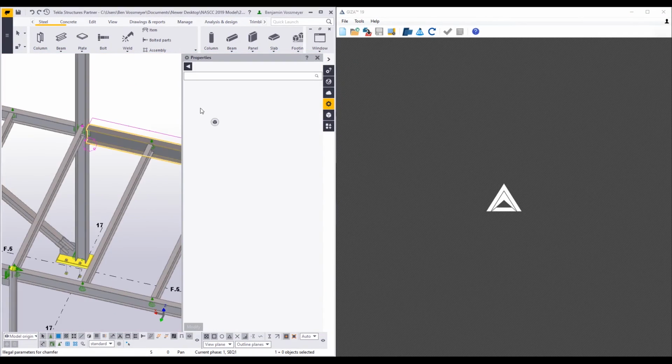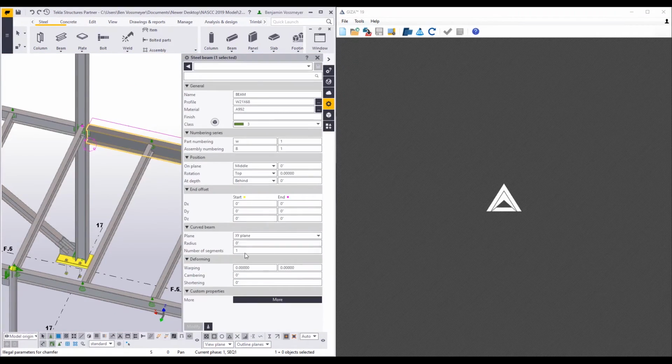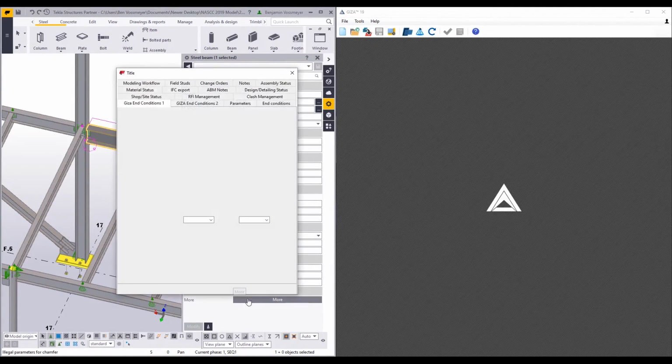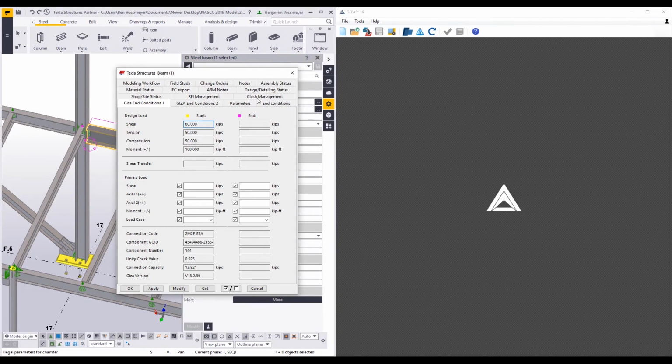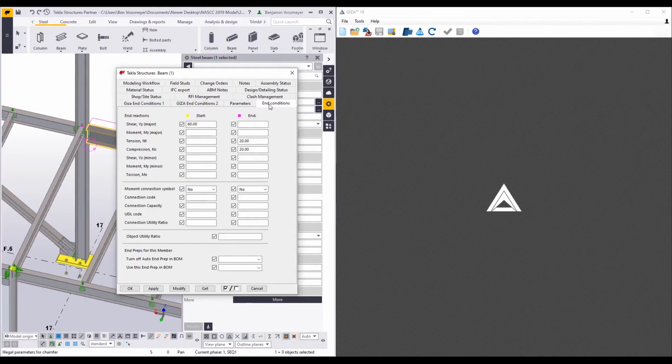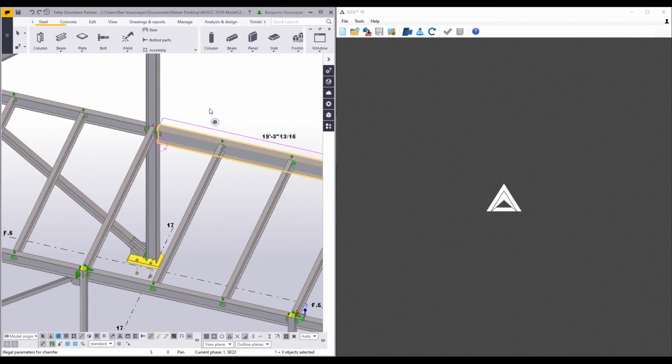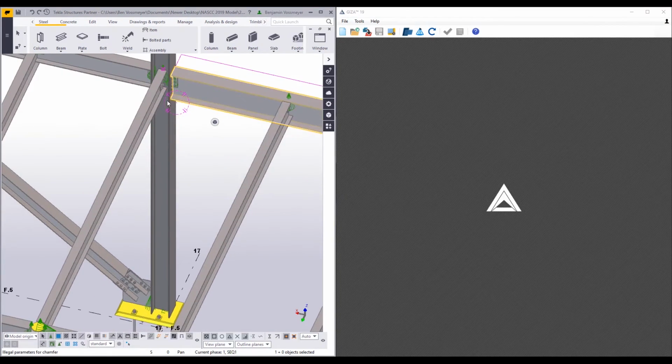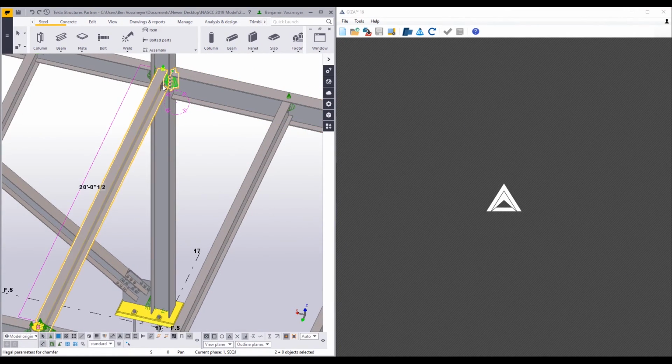If you would like to apply a specific load to a connection, open the user-defined attributes on the corresponding beam for the connection. The End Conditions tab is where you will define the load for a specific connection. If these values are left blank, Giza will default to the %UDL value. Once everything is filled out in your Tekla settings, you are ready to grab connections.